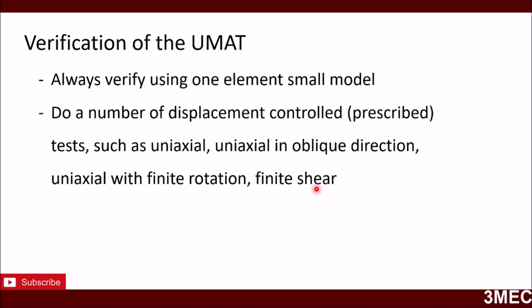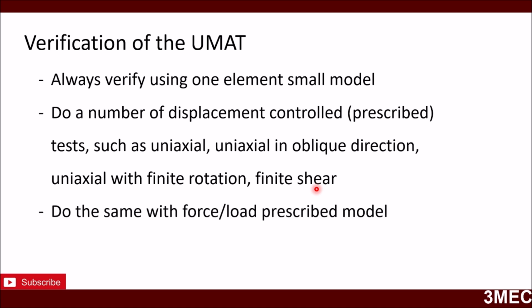So try to deform in all possible ways and see that your UMAT behaves the same as the normal linear elastic model in ABAQUS, because a linear elastic model is already available in ABAQUS, so both of them should give you the same results. Also you have to do the same with a force model. Instead of applying a displacement, you can apply a force, repeat the same test, and see if you get the same results as in the default ABAQUS model.